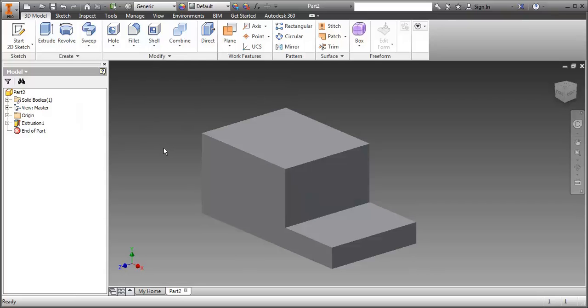I look at the parts like I'm machining them, and this is how I would tackle it. I would get a block, I'd square it up, and I'd cut the notch out, and then put all the other features in from there. Now you can pretty much go anywhere you want to create this model. I'm going to go ahead and put the counter bore hole in. So the counter bore is going to go on this face here.